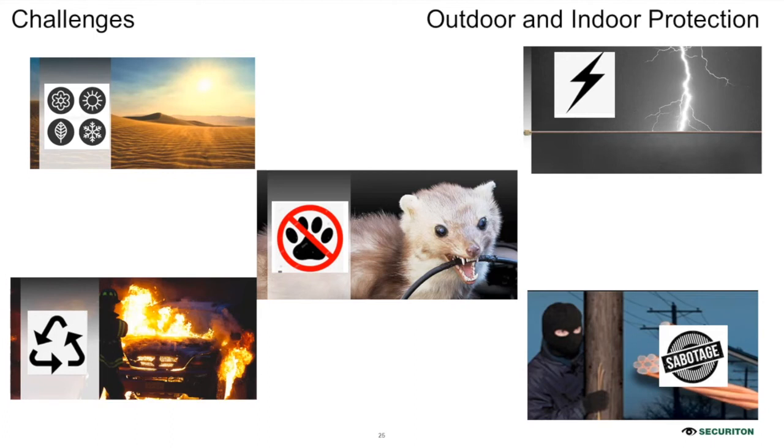the ADW may perform differently, so it has an adaptation that it can read and adjust by itself, so we don't have problems of weather giving you a false alarm, or it not working during different climates. Lightning, as this question was raised before, is a common problem when you are outside. So we don't have problems. Why? Because we have an SS tube or copper tube incorporated with a hard plastic tube before it enters the ADW. So if it is hit by lightning, it is not conductive. It will not conduct those signals back to the ADW component itself.